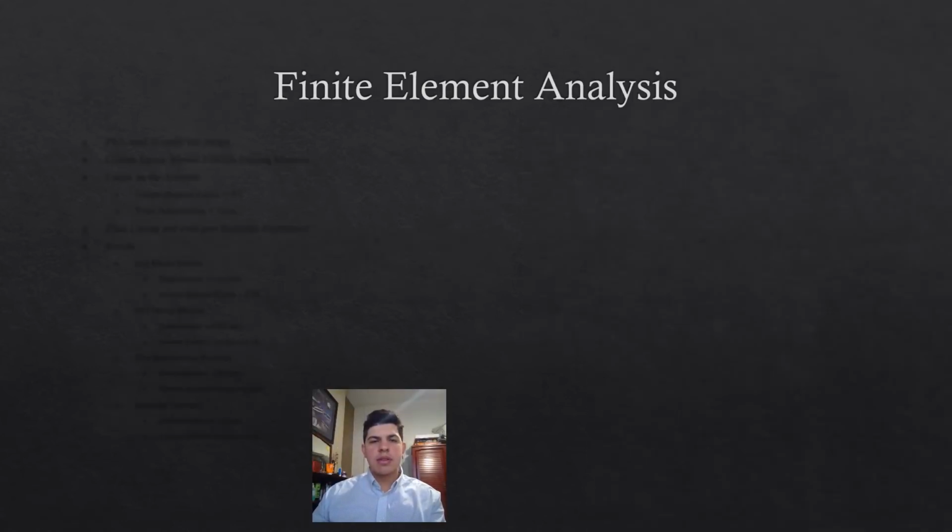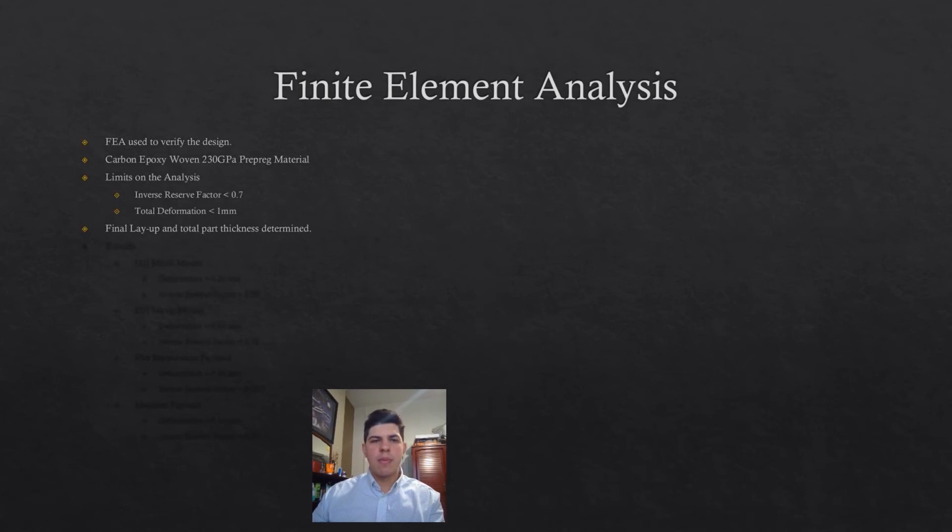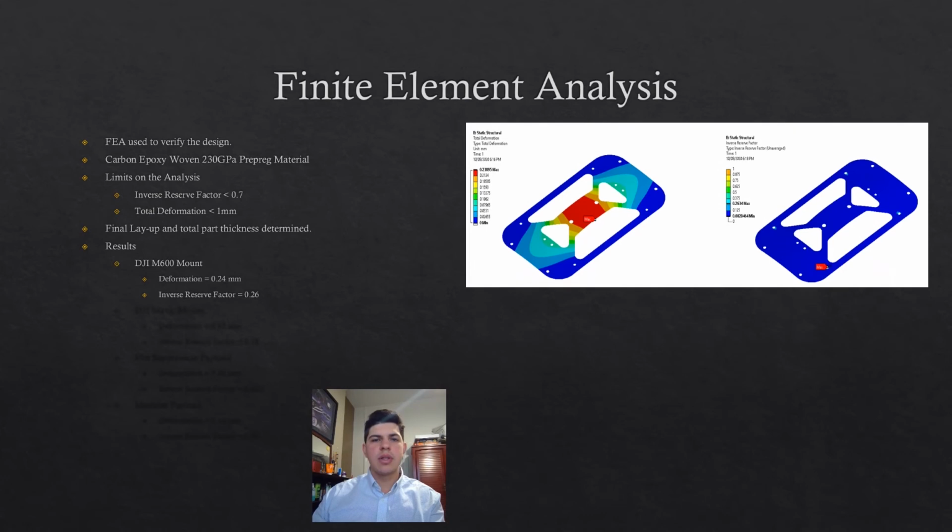To verify the material selection and determine which components perform under varied loading conditions, FEA was used. The ANSYS Workbench software was employed, and using the ACP pre-post module, each component's overall thickness and layout was determined. To ensure optimum performance, a minimum inverse reserve factor, which uses different composite failure criteria to ensure the component does not fail, 0.7 was established, with 1 meaning failure. Additionally, a maximum of 1 mm total deformation was also used to ensure performance.